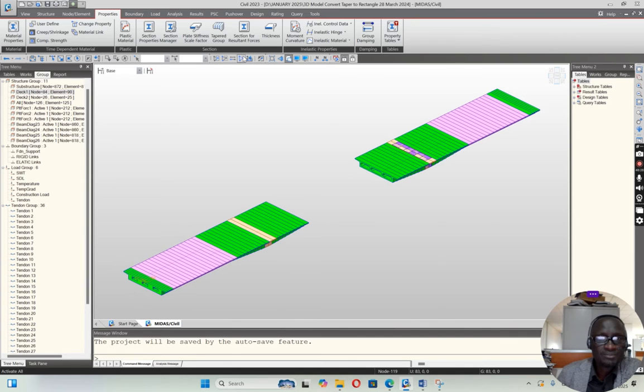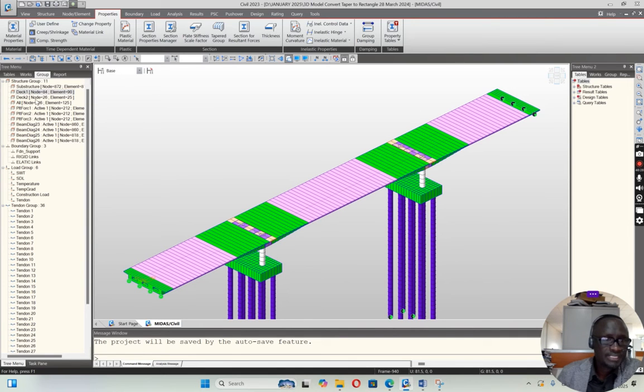So you are able to do now that's the deck 1. So that is deck 1. So deck 2 is now here. When now you have diverted traffic in this direction, you are able to remain with the middle deck. So you can now prop it, work on your formwork, work on reinforcement, work on the tendons, and then cast, and then tendon it. You tension it after it has gained that minimum strength you want.